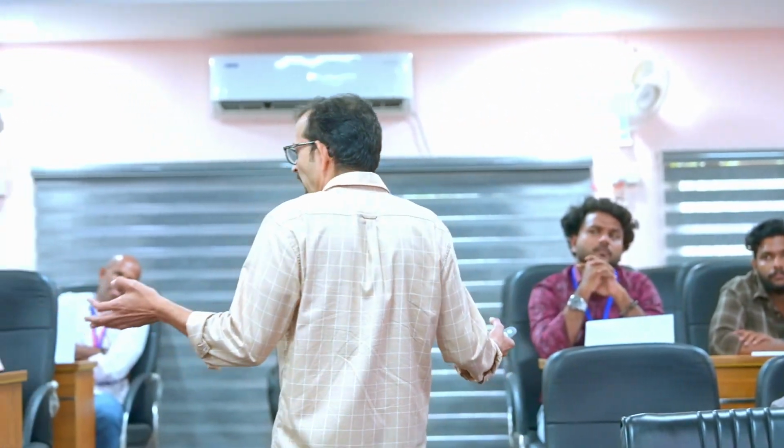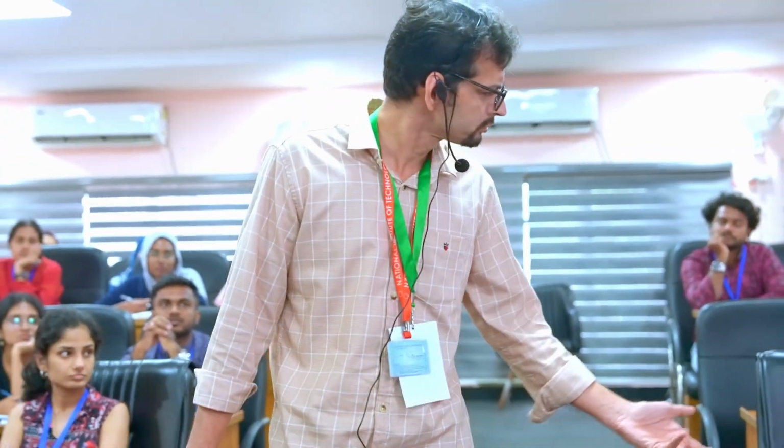I would say surface tension should be dominant, right? Because if you have a large puddle of water, the gravity will be having impact on that, right? So I will take something like 2 microliter to 10 microliter. It's okay, Banu? Yeah. To measure the contact angle so that I will get a decent idea about the measurement of the contact angle, right?